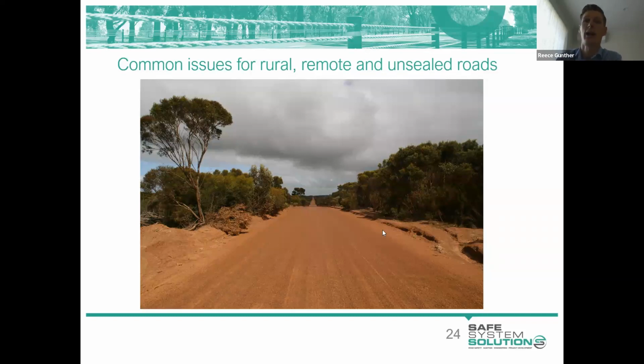The verges are high. You're right. They've gone through a bit of a cut here. They should be trying to push that verge away from the road. It would have a flow-on impact with drainage. So providing a flatter area would be nice, because that verge definitely presents as a hazard. With a strike, that would create vehicle instability and potentially a crash. So great pickups, everybody.